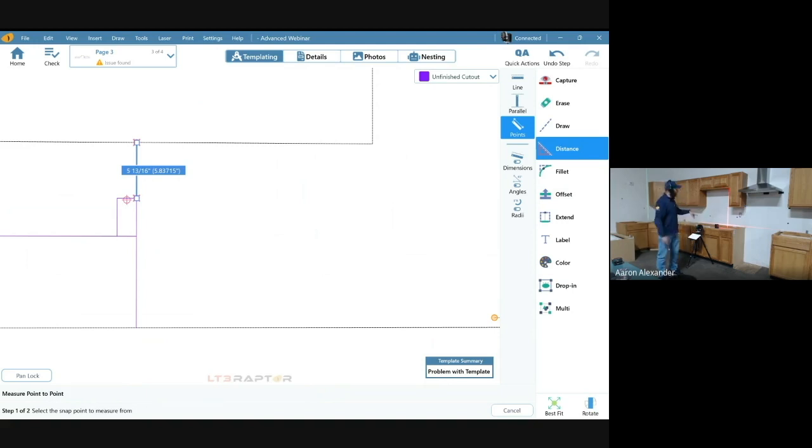Now I know 6 ways from Sunday that outlet's going to be hitting in the right spot, as long as we don't adjust the bottom of the backsplash. If you offset the bottom at all, you just change where your outlet cutouts are. So any adjustments we make have to be done to the uppers here, uppers only, right? Bottom edge got to stay the bottom edge, right?